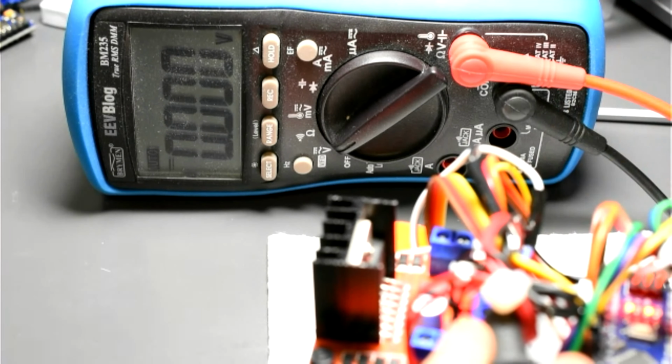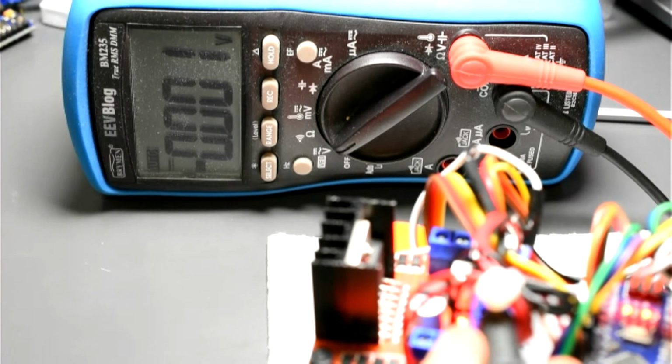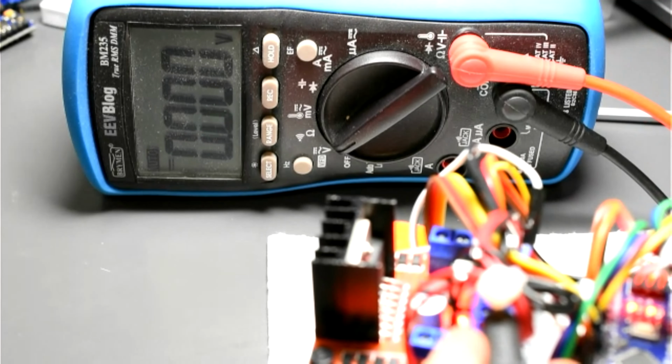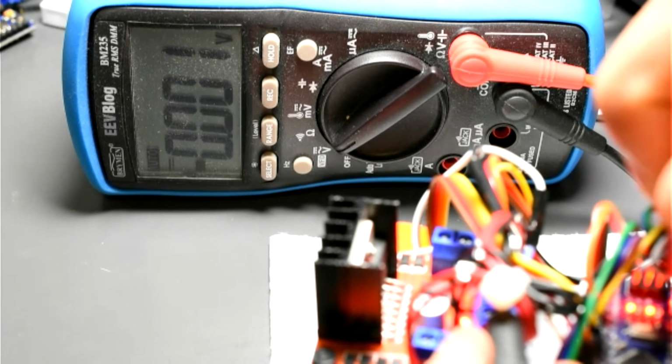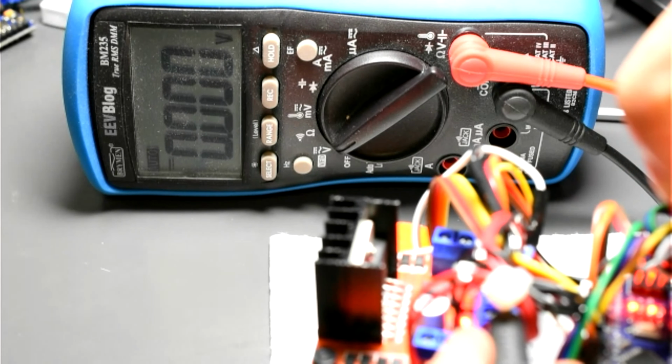And then if we go over here and measure V in, sorry, should I be measuring V in? Oh my god, I should be measuring 5 volts because I actually got 4.9. Okay, my mistake. I measured the wrong pin. I measured V in instead of 5 volts, and there was a 0.5 volt drop. It was like, crap, something's using a lot of current.